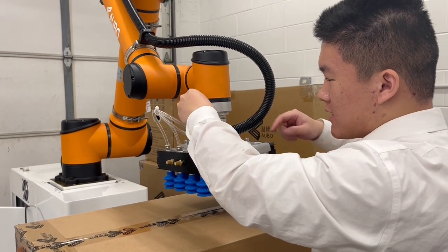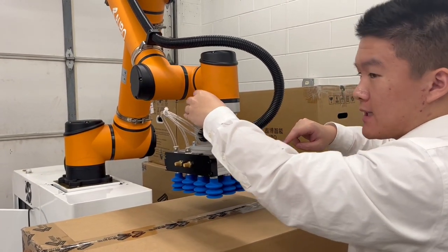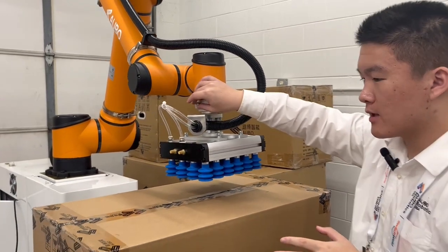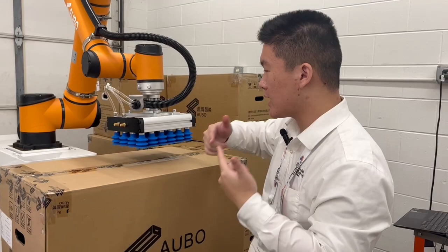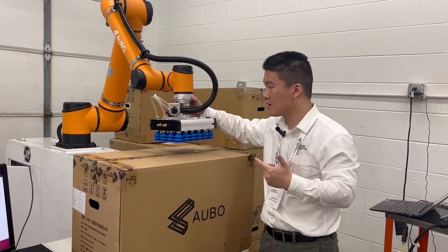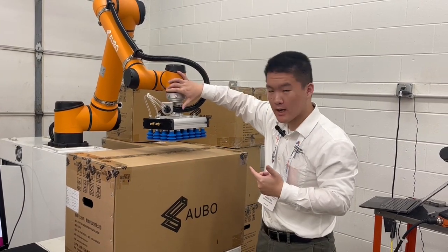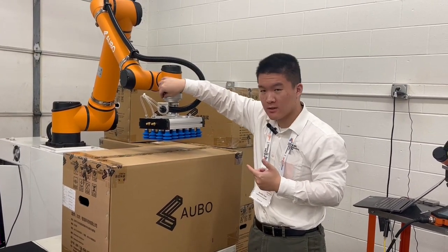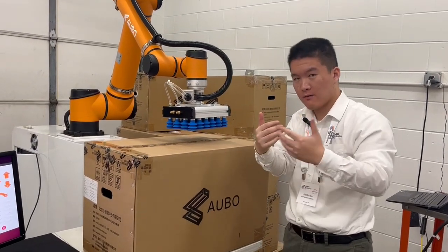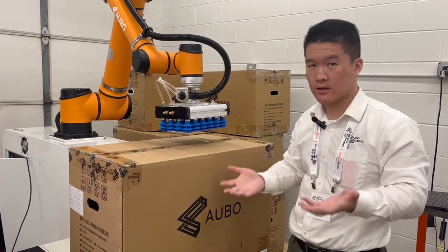Basically, when you calibrate the point, the rotation of this joint 6 determines the orientation of the conveyor. And the direction of this particular connector in the middle here determines where the product is coming from, basically the orientation of the conveyor.